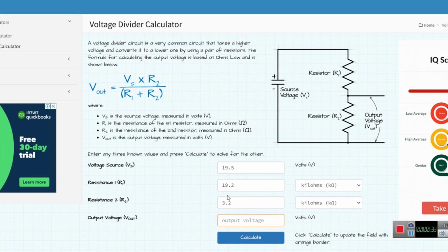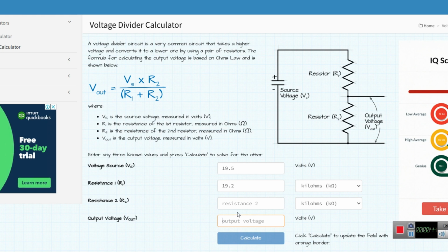If we wish to change the R2 resistor for the desired output voltage, normally the voltage on the AC detect pin will be around 2.6 volt. So we can set that voltage here, and if we calculate, we can get a resistance value. So it should be 2.9 volt. Approximately the voltage is okay on the resistors, I think.